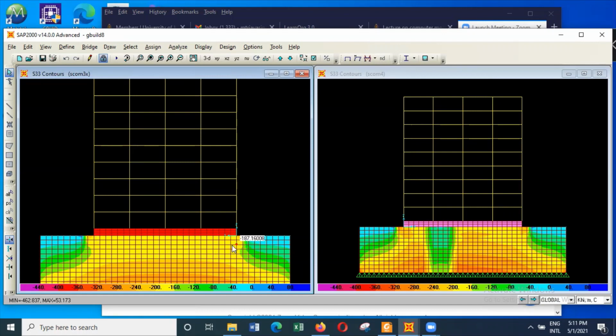If you can create the basement in a similar manner. Whereas in the case of a basement, you may not have all the partitions, but you will have a slab. But you might have a thicker raft at the bottom, and then the void. And because we are removing part of the soil, that weight can be compensated for the weight of the structure. So that's the advantage of a cellular raft.